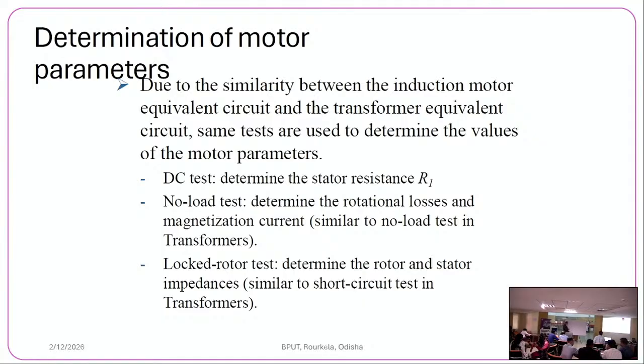So you determine the stator parameters, resistance parameters R1 and R2 dash. Here also you determine XM, magnetizing reactance, in no load test.